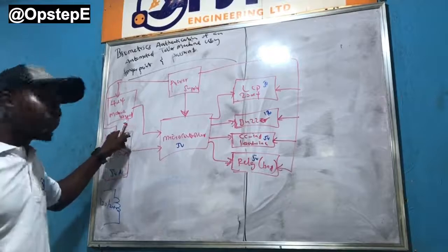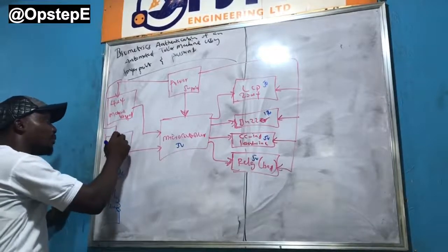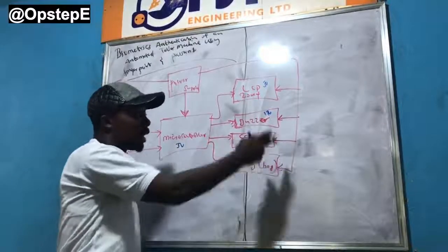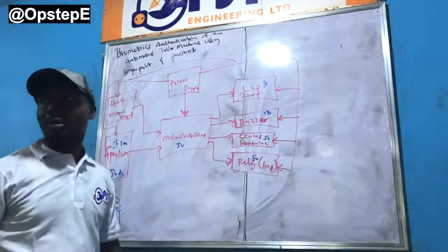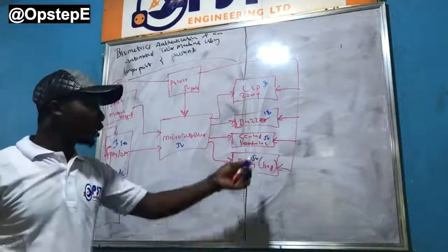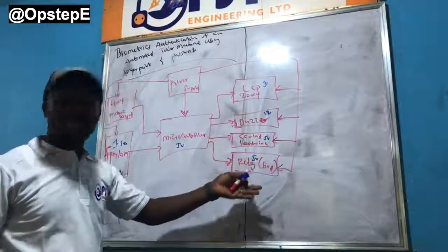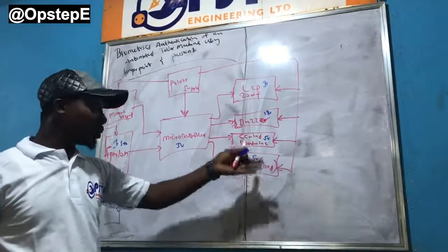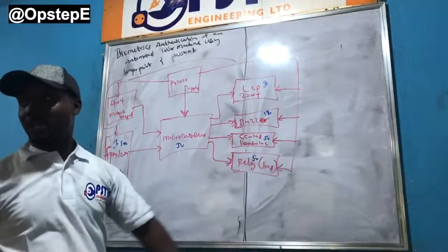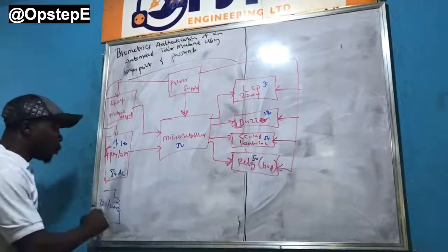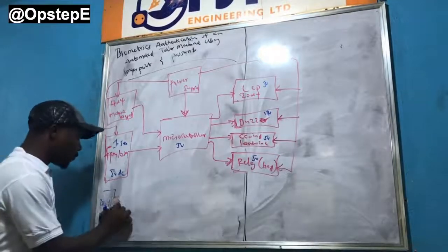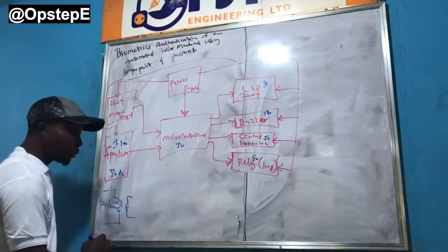So let's assume that this is 1.5 amps. Of course, the line that will go to the relay would be at maybe 10 milliamp. Your relay coil should not be more than maybe 80 ohms, or 30, or 300 ohms. Divide that by the 5 volts and you should be able to tell the current that is playing. My point is, if we get a 1.5 amp transformer, we are good. The transformer, of course, is a step-down transformer.